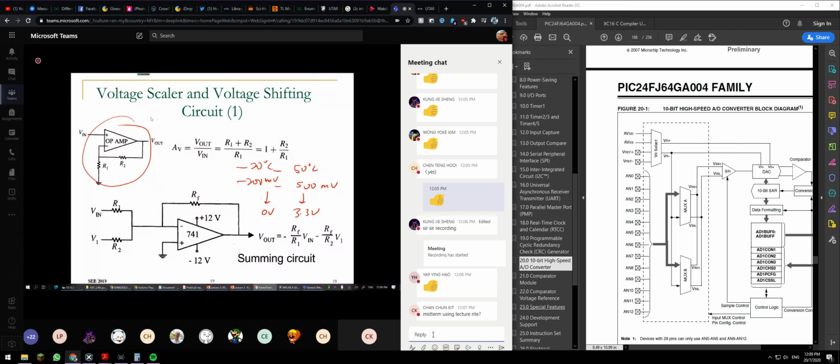And in situations where you have a problem of a small value from the sensors, for example, the output from a sensor is from negative 10 millivolt to 10 millivolt, or like here, 200 millivolt to 300 millivolt. So in order to achieve better accuracy, normally we try to shift this, for example from negative 20 millivolt to 0 volt, 500 millivolt to 3.3 volt.